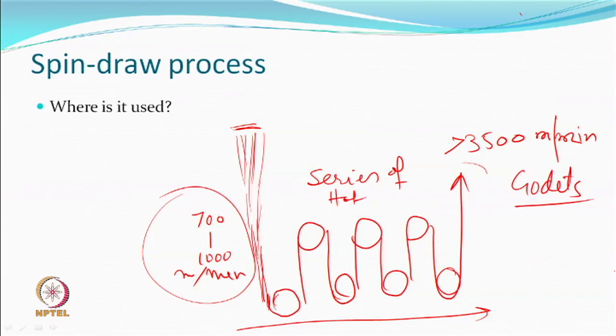If the speeds are the same, they can combine. That is, the yarn can be fed at a very fast speed and then again taken out at a fast speed. So, here at the end, this is a fully drawn yarn. This is the input. So, a spin draw machine can become an input directly to the BCF.